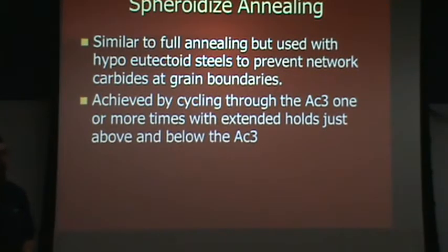The carbide along the grain boundaries, we often refer to it as a network carbide, and it's very brittle. And it means the part itself is very brittle. So we typically don't want that to happen. So for those parts, if we're not immediately going into a fully heat-treated condition, fully hardened condition, we would go into what's called the spheroidized annealed condition. And so that allows the extra carbon or carbide to form a spheroidal shape, and now you don't have the brittleness issues that you have with the network carbides. And so again, this material tends to be relatively soft, it's machinable, formable.